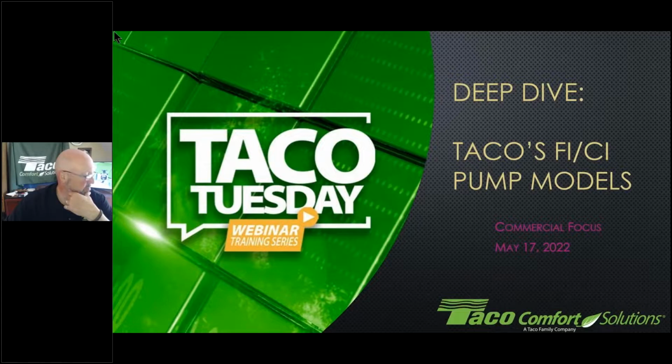It's going to run at a constant pressure of 10 foot head, and as a result, the zones are going to get the same flow in October as they do in January as they do in April, because you have to run on a performance curve. Once you set a constant pressure at 10 foot head, that's the performance curve it's going to run at. Now the speed will vary, the electrical consumption will vary, but that flow and head will remain consistent as zones open and close, no matter what time of year.